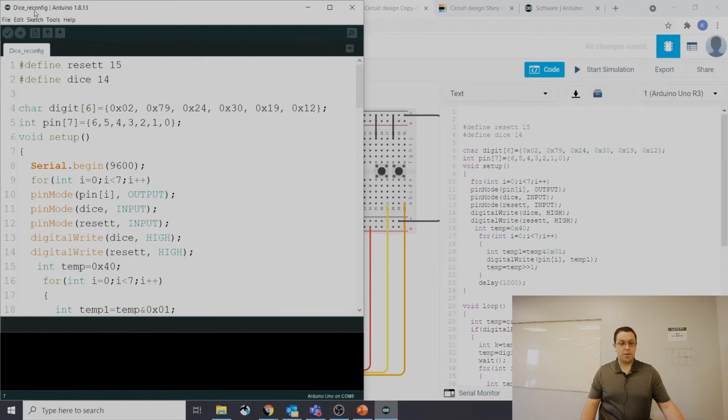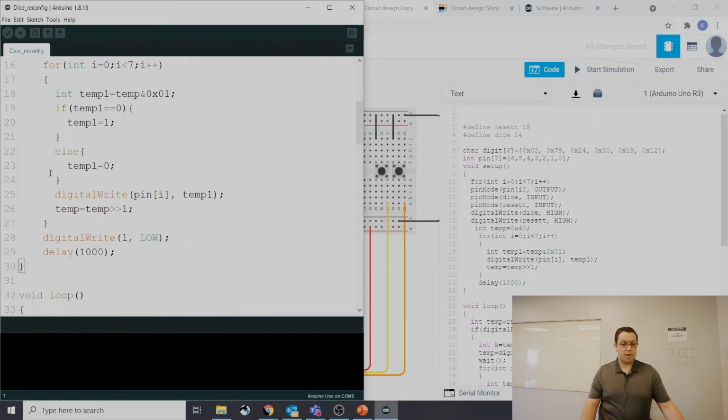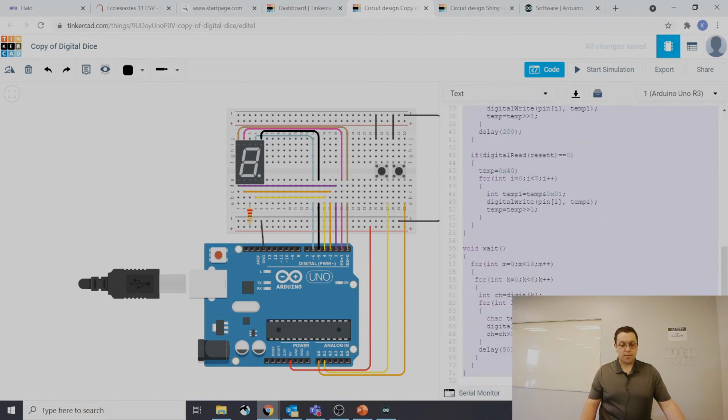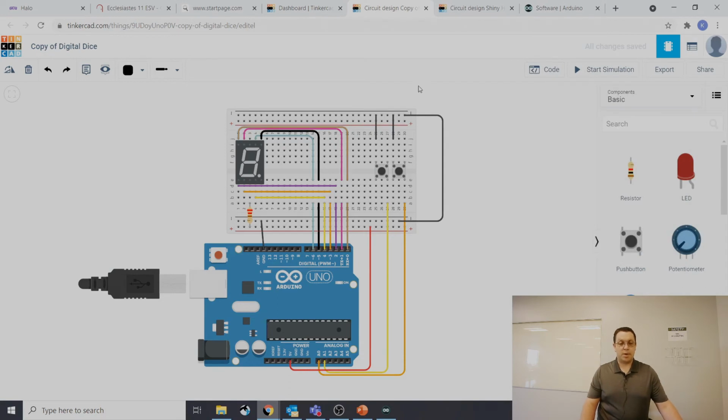And yeah, this is a previous version that I had where I've made some changes to things. We'll talk about that in a minute. The theory is you're supposed to be able to download the code, open it in the Arduino IDE, and load it directly onto the board. Instead, you're going to have to start a blank sketch, copy the whole block of code, and paste it into the Arduino IDE, and that's as simple as copying and pasting in a Word doc.